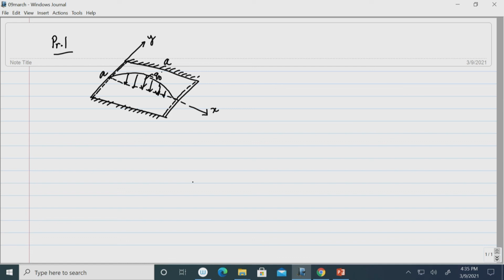Okay. Then if I see the variation along y axis, again it is sinusoidal. So, in the two direction load is sinusoidal, that means if I write the load function, that can be written as q x y is equal to say intensity is q naught sin pi x by a sin pi y by a, because it is a square plate. So, the dimension of the plate is a by a. Okay.